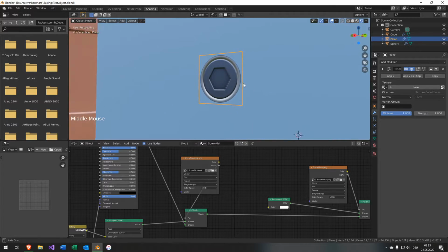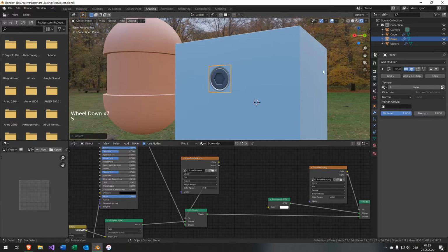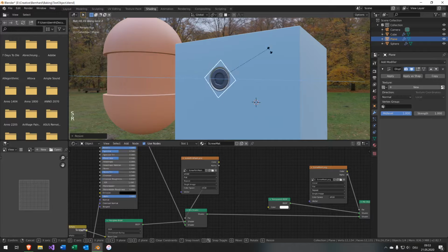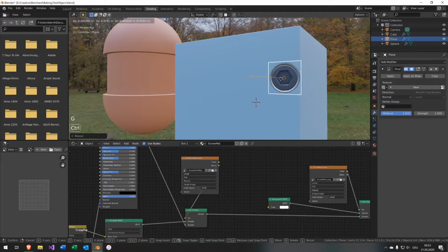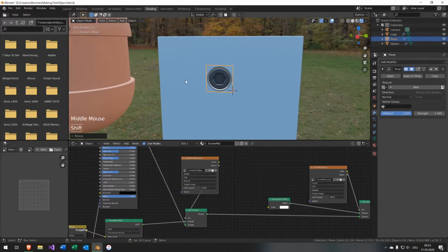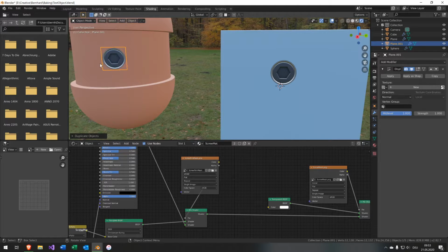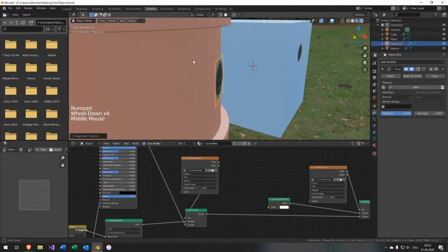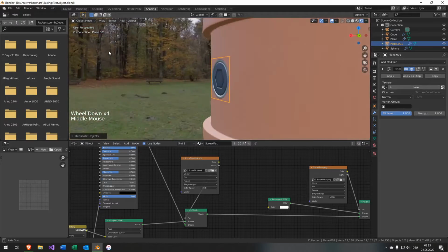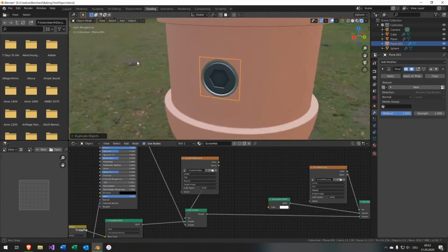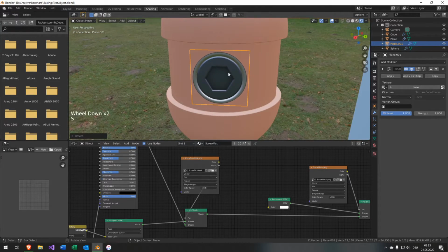We can now exchange our material if we want, but we can also resize it. We can rotate it, move it around. When holding the Ctrl key, it would automatically align. And that's one big advantage of using the displace modifier, because it will also displace when you move it around. If you would have moved it with the transform operation, you would have to repeat this step again after moving the decal.